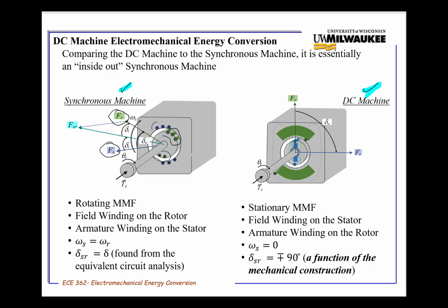And we've got these blue windings, and I'm just representing the combined three-phase winding MMF all together as one winding. You'll have the MMF pointing out here, and it's rotating, and it's off from the field winding by an angle.